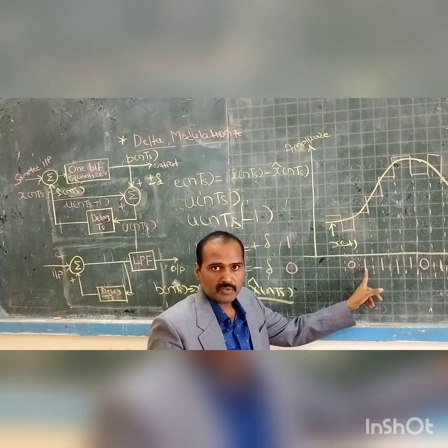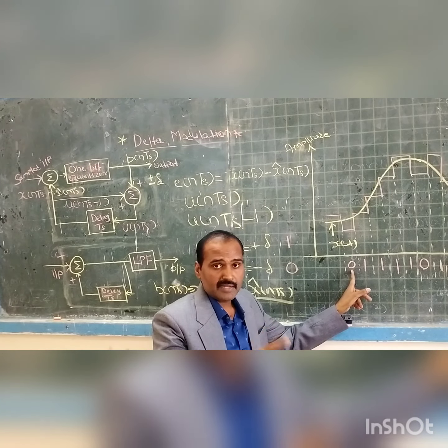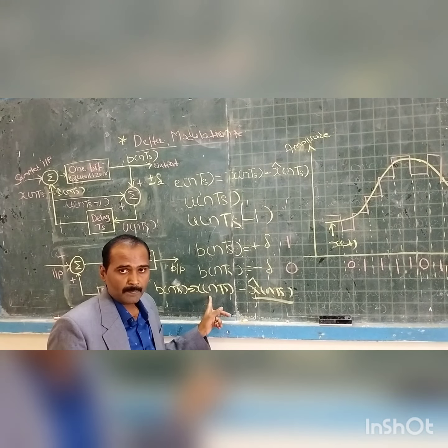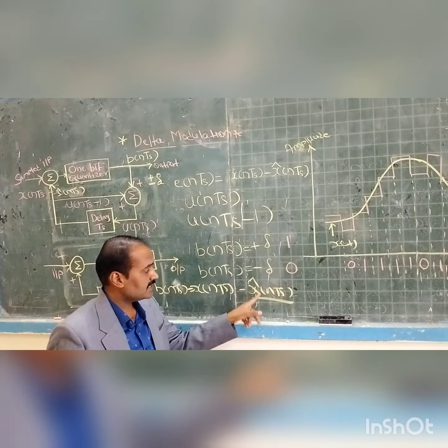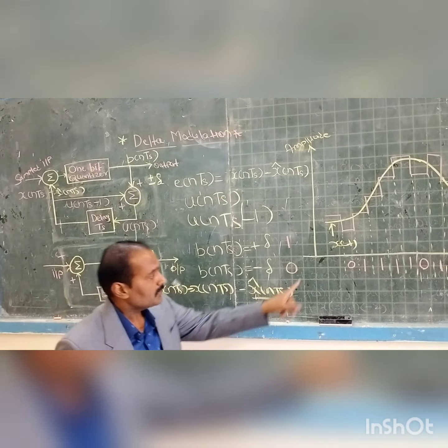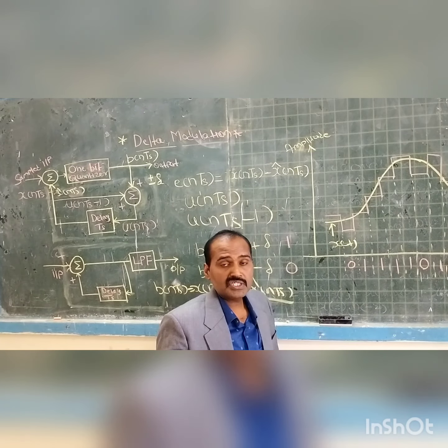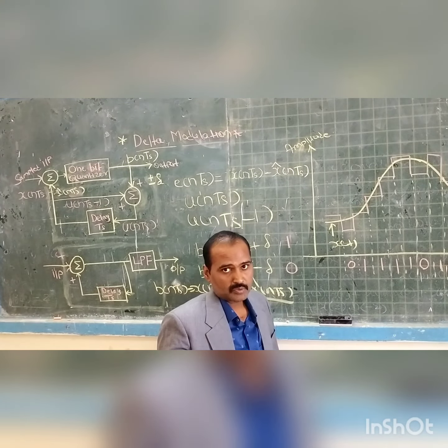How will the modulator come to know that a sample is to be encoded with binary 0? If the difference is negative. The difference between which two signal levels? The difference between the instantaneous value x of nTs and the previous sample value of the staircase approximated signal, denoted by x cap of nTs. During each and every signaling interval this is to be done, and accordingly that difference is encoded with respect to 0 or with respect to 1. So this is how this delta modulator will work.